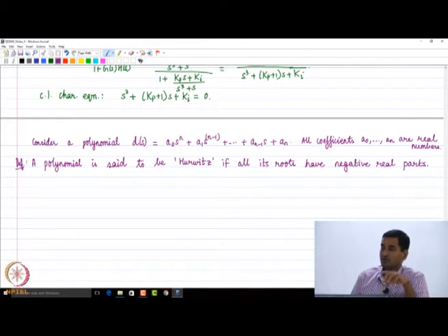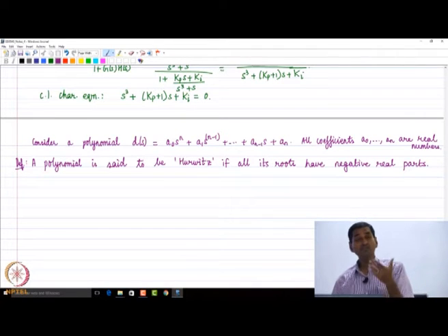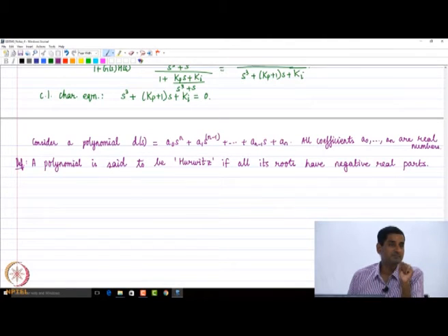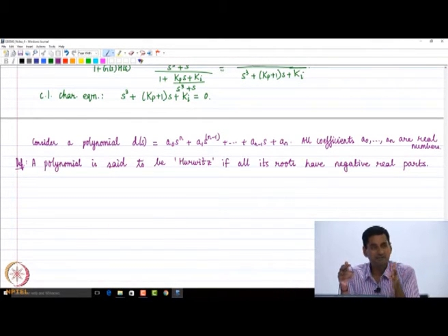So how is this related to our control design? We want all closed loop poles to be in the left half plane for closed loop stability, right? We have figured it out from our derivations previously, how we correlated the physics behind BIBO stability to the mathematics. Now how do I get the closed loop poles?